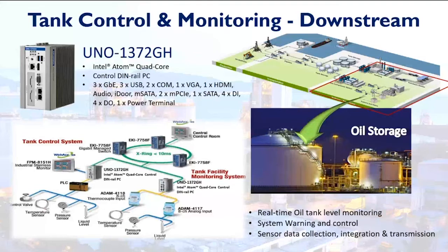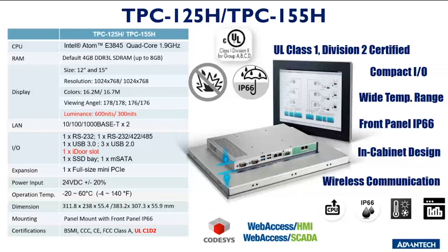The Uno is like a gateway to connect to the PLC and the IO module, collect the data from the different sensors, and transfer the data to the control room. And of course, on the field side, we also select an industrial monitor to connect to this Uno for HMI implementation.